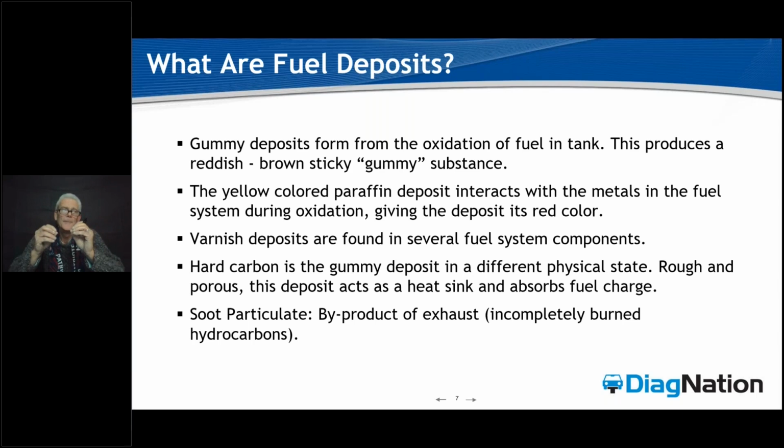And so the time to fouling of that engine is 1/3 of what it used to be in the multi-port world. What I mean by that is that you can get a lot of these GDI turbo cars that are short trippers, guys, with drivability problems that are creating check engine lights and in some cases having the car towed in less than 10,000 odometer miles from new.